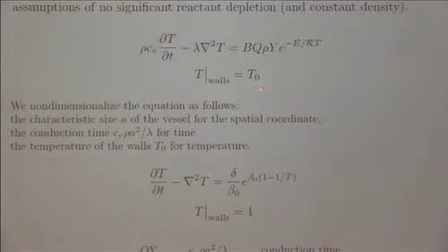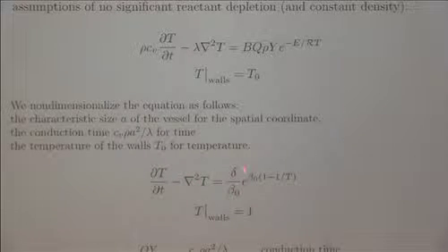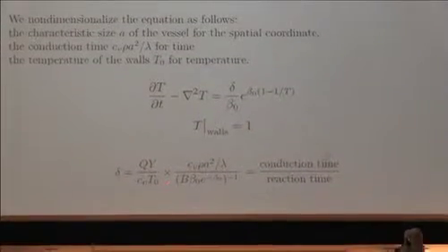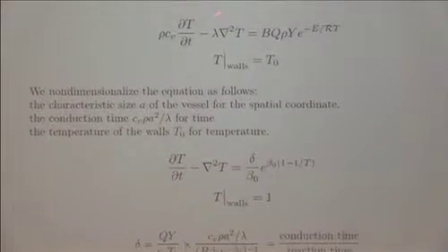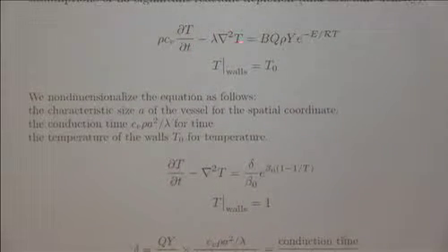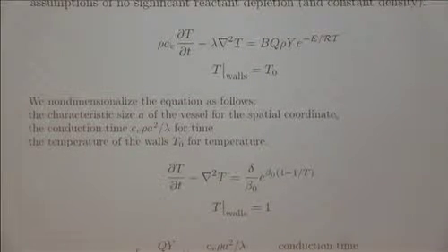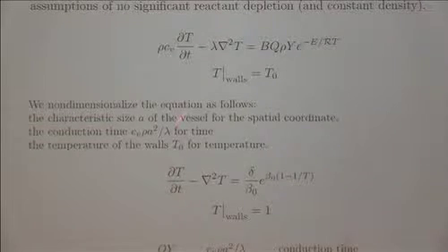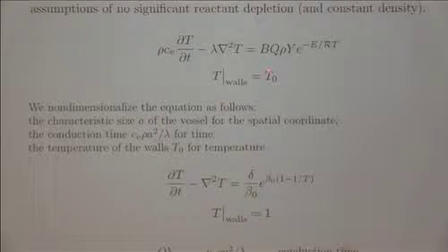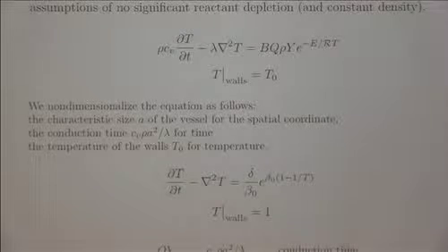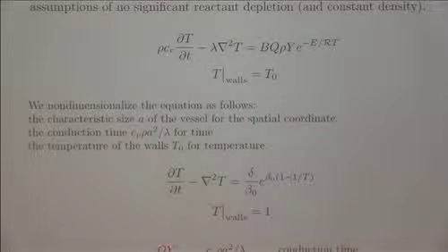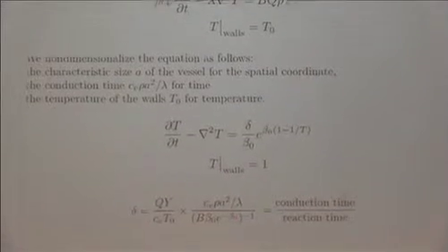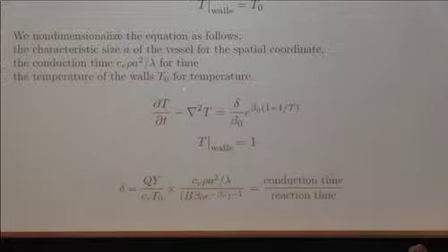Since I'm not going to be solving the time evolution, I did not specify the initial condition, but in general, you should specify one. Now, if you rewrite this problem in dimensionless form, again, there is only one parameter that pops in, and this is this little delta, which is actually quite similar to the previous one. By the way, just an important point: in the previous problem, instead of putting the Laplacian, which is the Fourier law of heat conduction, we replaced this with a phenomenological term, which is T minus T naught, right? But this is, of course, the more accurate description because the loss occurs through the walls, and it's because the wall is at a temperature T naught, which is different than the temperature inside the vessel. And temperature inside the vessel need not be constant. Okay, so the only parameter that appears is this. Again, it's the heat release multiplied by this ratio of conduction time to reaction time. It's like the Damköhler number that we have seen before. And the equation is written here.